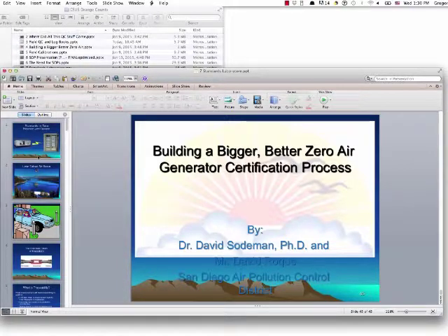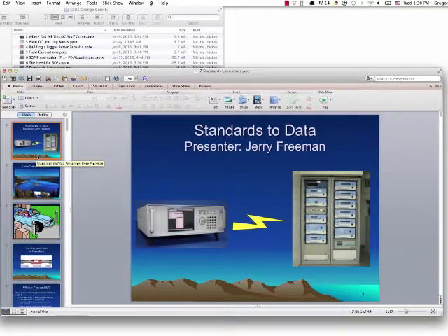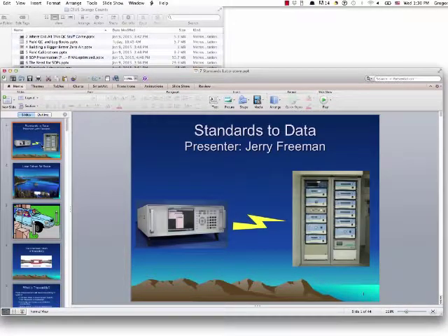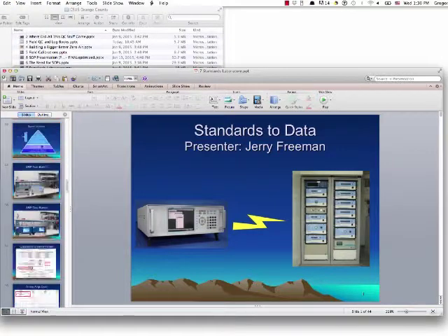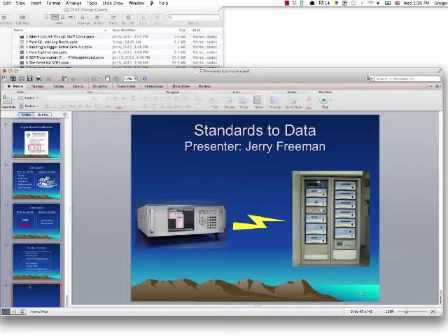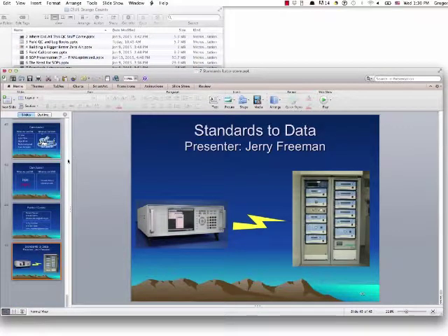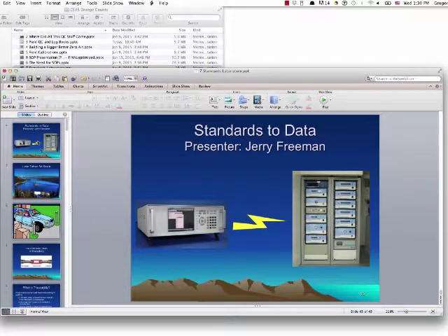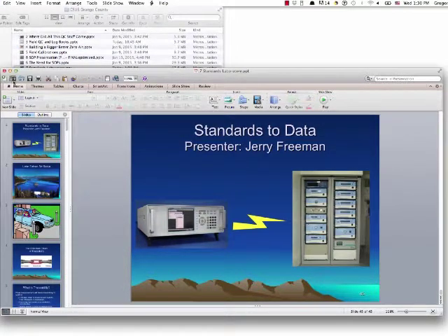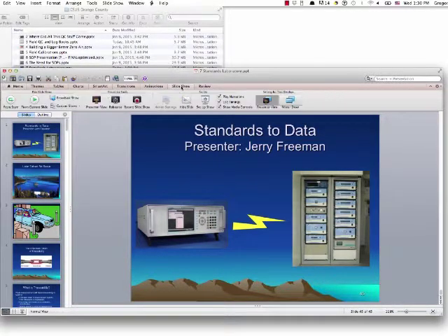Well, it depends on the analyzer. In the SOP for the specific analyzers, we have what type of maintenance typically would require a calibration. And when you're verifying after your maintenance has been done, that's why you want to make sure you're using a verified transfer standard that's been certified. And I would assume if you were in question, it'd probably be a good idea to check it anyway, right? Right.